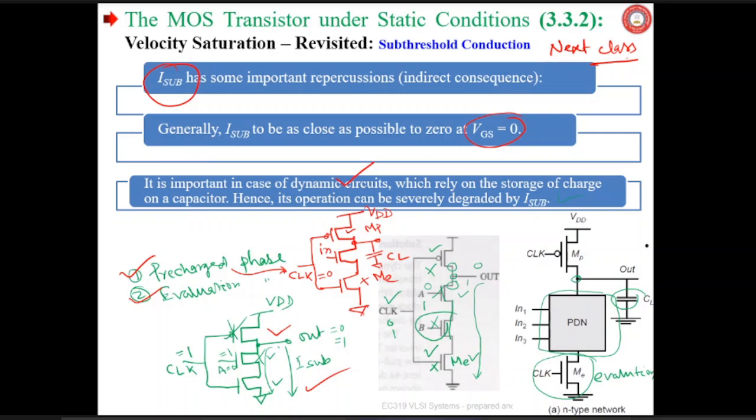You said it correctly, tell me. Interconnect capacitance, then drain diffusion capacitance, and the third one is COX of fan out, the gate oxide capacitance of the fan out gate.